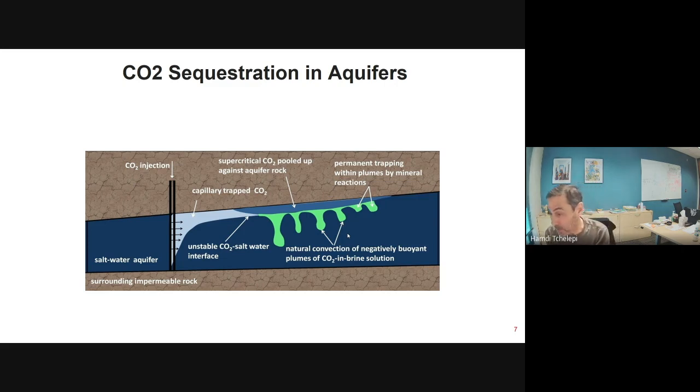So an important point to mention here is that supercritical CO2 and saline water are expected to be immiscible with each other. So now you have two different fluids with two different viscosities and densities and wetting characteristics sharing the pore space, but some of the CO2 along the gravity current actually gets dissolved into the underlying water, and that density difference of the layer saturated with CO2 with respect to the underlying water without CO2, there is enough of a small density difference to drive a convective instability.